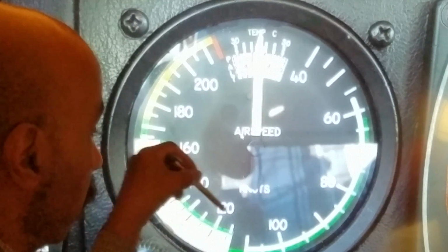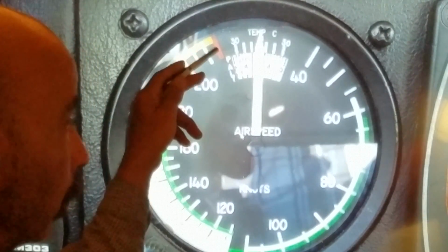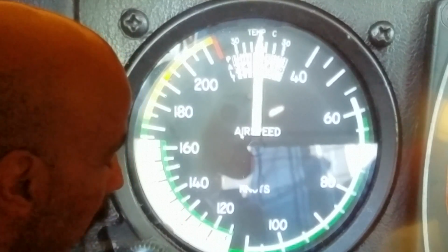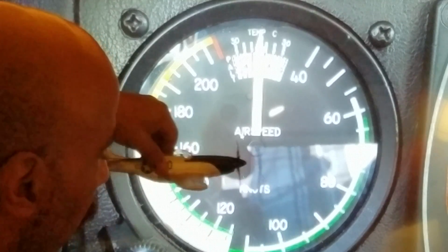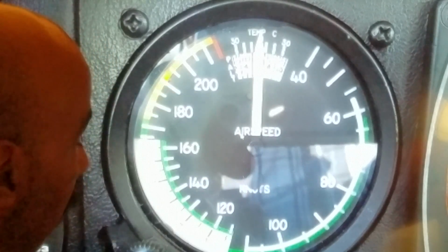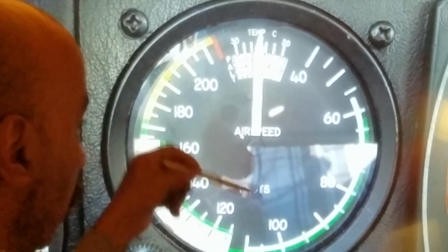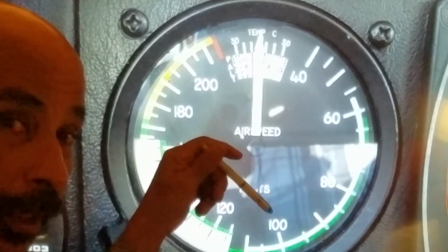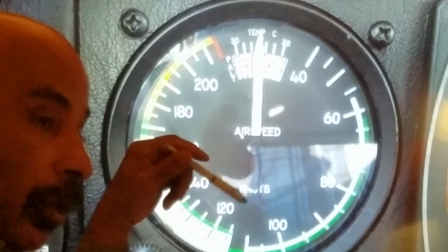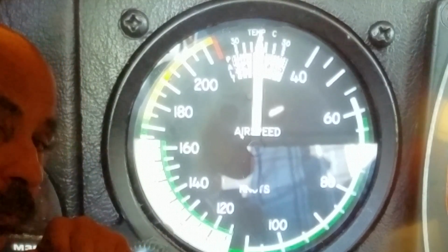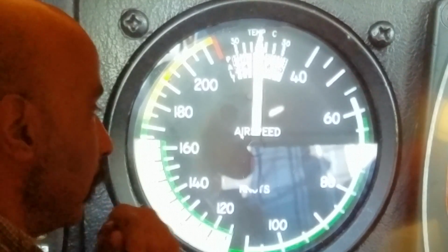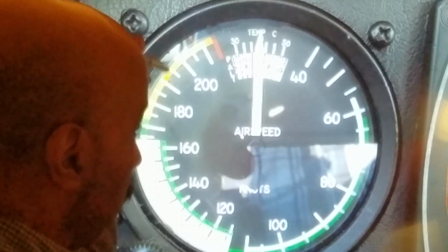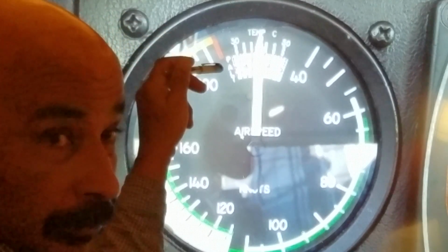During normal cruise, chances are you won't be able to approach the red line speed. At a set altitude and a set power setting, even at maximum power setting, typical airplanes do not approach that red line speed. The only way you can get the airspeed that fast is to be in a dive, typically. I'm not going to say all aircraft don't have enough power to reach red line in normal straight and level flight attitude, but typically you'll have to be in a dive to get to that speed. It's legal to go to that speed, but don't exceed it.